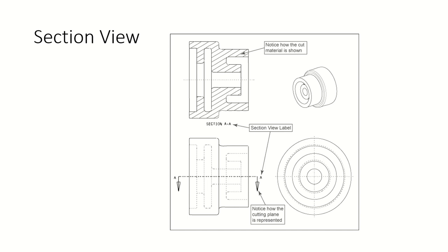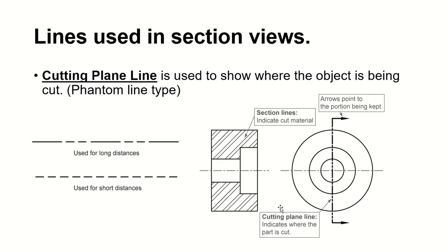All right, lines. We're going to use different lines, of course. This is for short distances, and that's for long distances in your sectioning drawing. Okay, cutting plane line. The first type, long dashes. The second type, you're going to use short dashes for your short distances. Long, short, short, long, we're going to use for long distances.